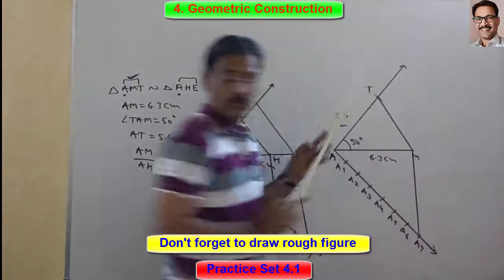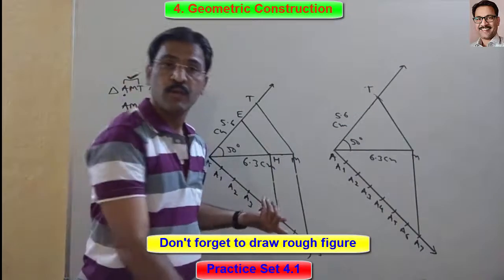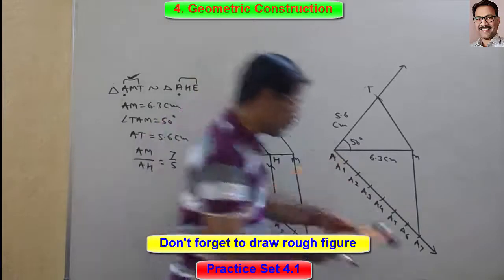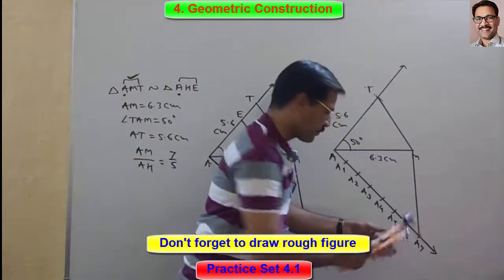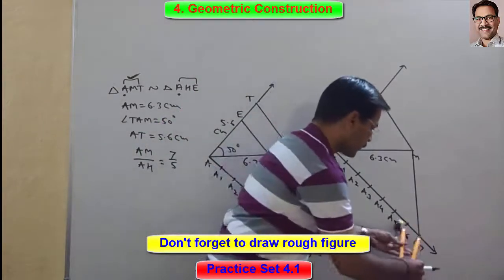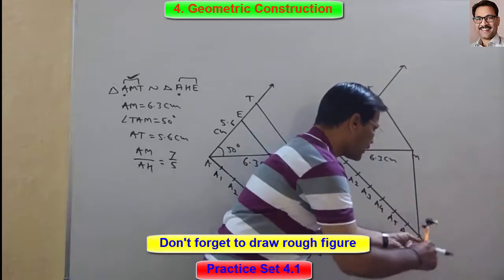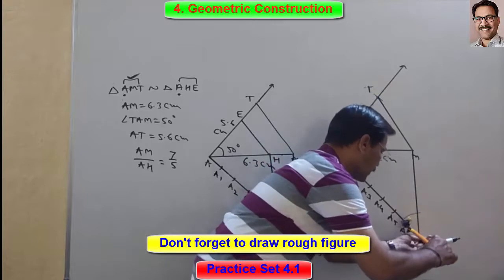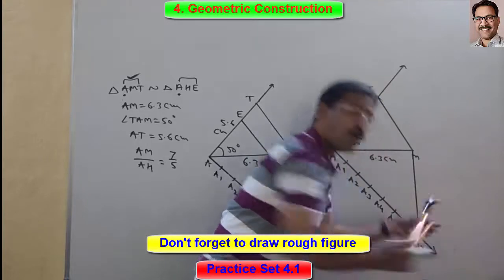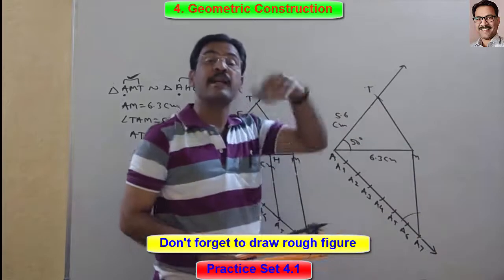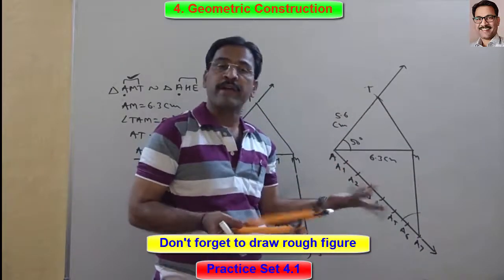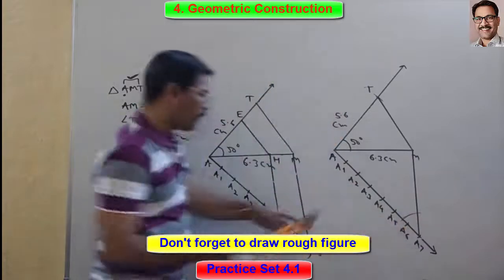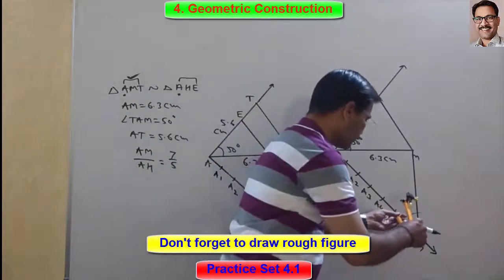Okay, now the next part as usual, but that should be inside. I'll take some distance, that should be more than A6, A7. Like this. Now put the compass on A7 and draw one arc here. What am I going to draw here? Congruent angles, like corresponding angles. When we draw congruent angles, then the two lines are parallel like this one. So on which side here? A5. I'll put it here on A5.